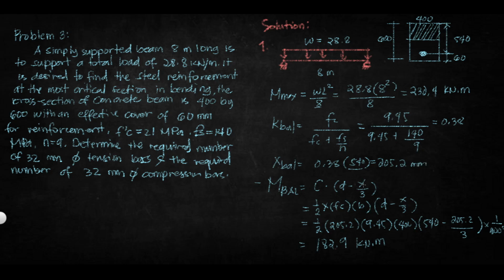So after solving for X balance, we can now solve M balance. So moment balance is equal to C. Ano yung C? Ulit, class? Okay, very good. C is the compressive force, times D minus X over 3. Yan po yung distance between the two forces C and T. Tama?